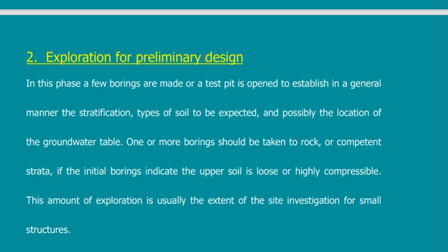Before you start constructing these items, just do a preliminary investigation. Instead of doing maybe 100 boreholes, you know what is a borehole? Instead of doing 100 boreholes, just perform 10 boreholes. These 10 boreholes, scatter them all over the site so that you can ensure that what you are going to see will be matching your expectation.